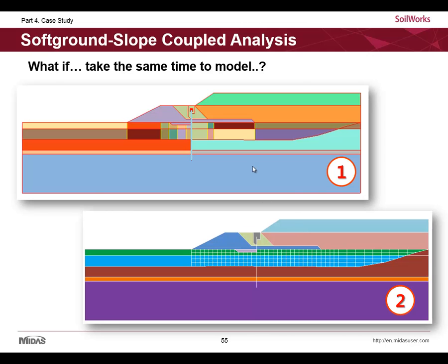In the case of model number 1, the area of soft ground is classified very well according to the geometry and material of the embankment: slope, load, sand, concrete. But in this case, this area has the same increase in strength, like cohesion and friction angle. So we need to take a closer look. Do you think it is reasonable that this whole area has the same increase in strength?